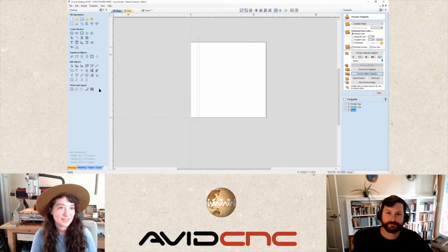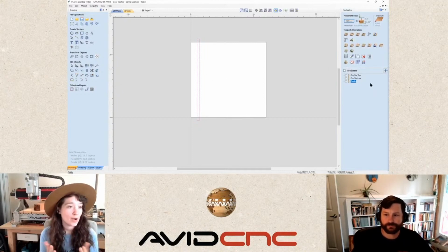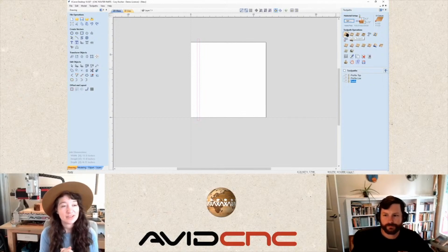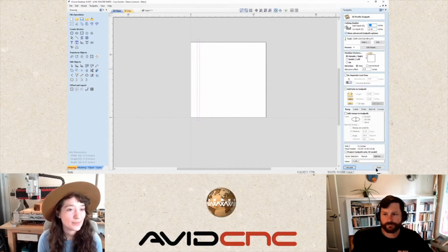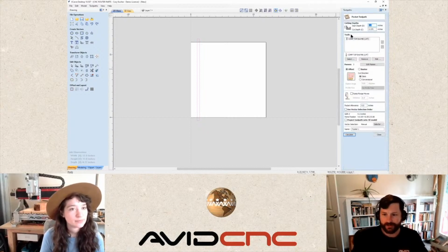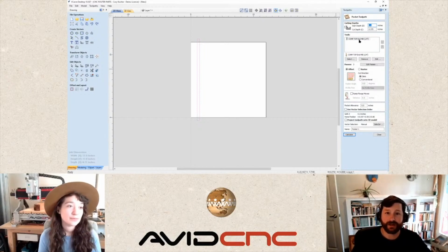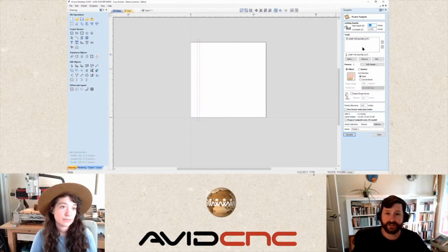I mean, this is also very similar because of the width of it. You could definitely do a profile interior or a pocket as well. I think I'd probably still go for the pocket just for the consistency. Yeah. So the pocket cut is going to be a similar type of scenario where we can use a compression tool if the depth of cut is deep enough where we can get that down cut part into that top veneer. But the width of your slot could help dictate which tool you look at. So for a slot smaller than this, you might look at a smaller end mill, but I do feel like our 1/4 inch end mill is going to be adequate here.